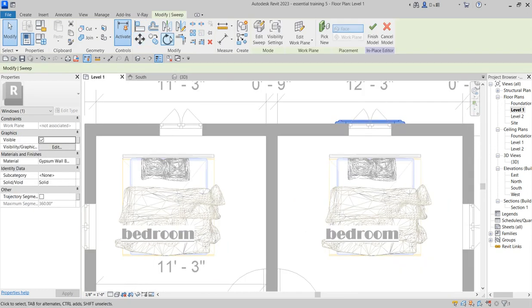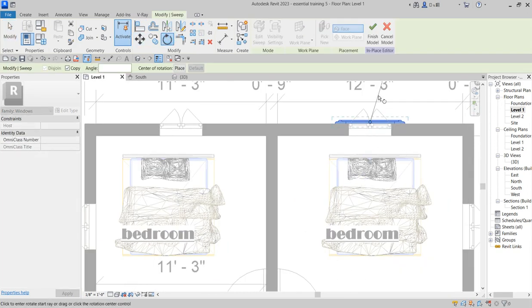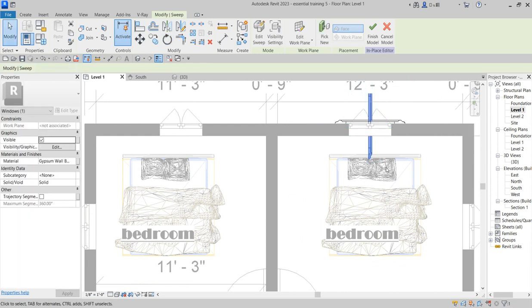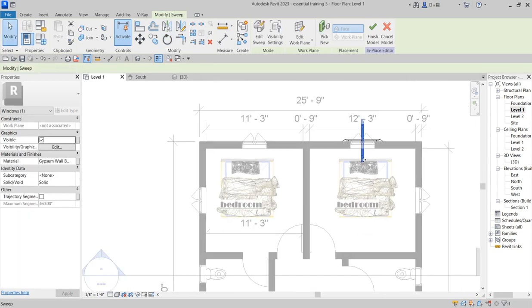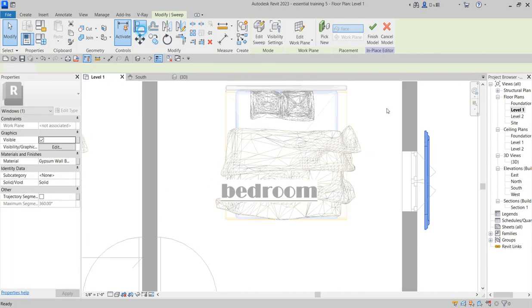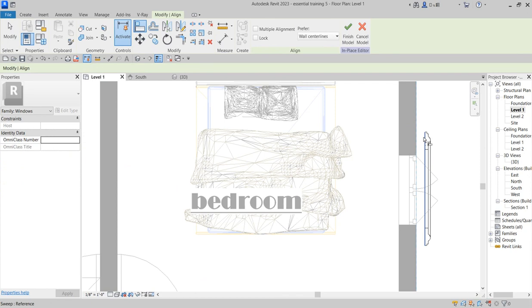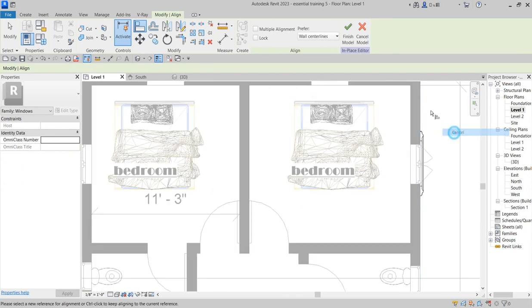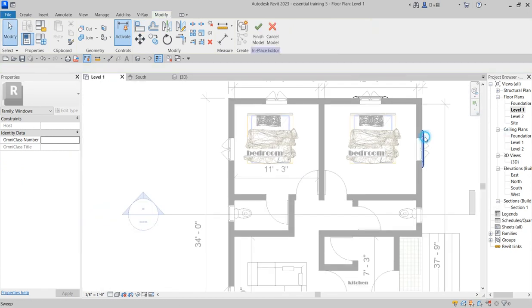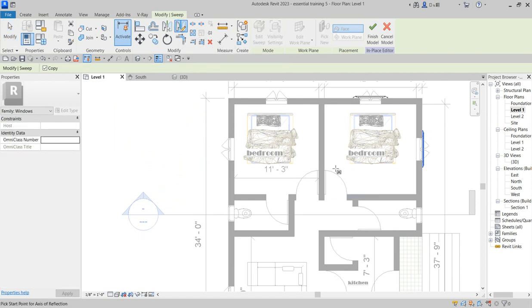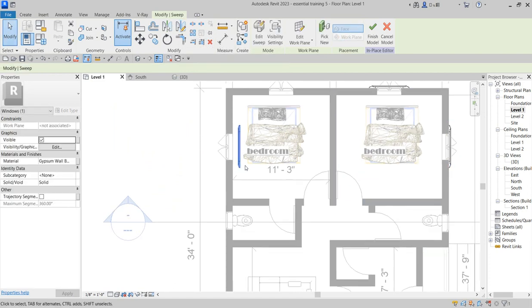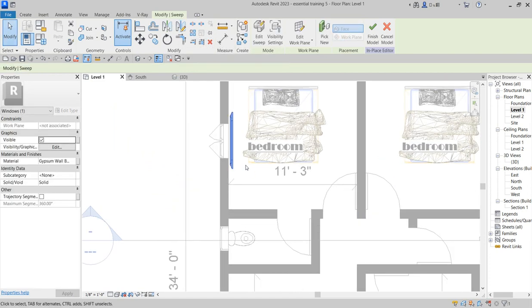The second one, you can copy or rotate. Then you type 90° on your keyboard. Just type 90, it will rotate itself. You can bring it out and align it to wherever you want it to be. So at the elevation, which is the side, you are going to align it again. You can do the same thing here again by saying mirror this one, because you are using them at the four sides of the building.